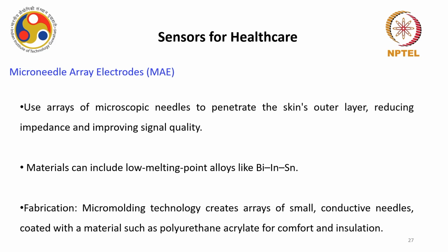A number of advancements exist in this kind of electrode. Then we have microneedle array electrodes, MAE electrodes. Basically, it uses an array of microscopic needles to penetrate the skin's outer layer, which reduces the impedance and improves the signal quality. So you can say that it's a kind of minimally invasive technique for ECG measurement.